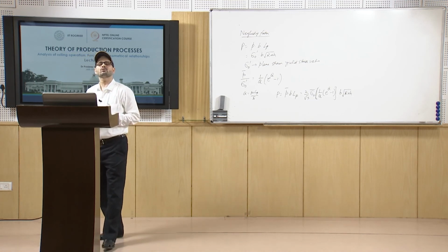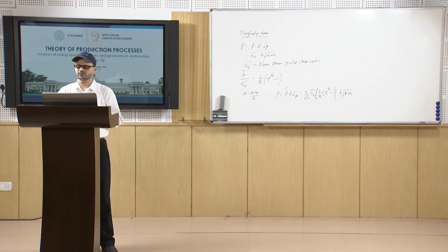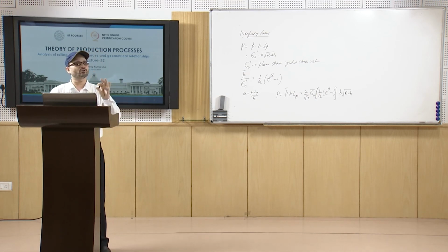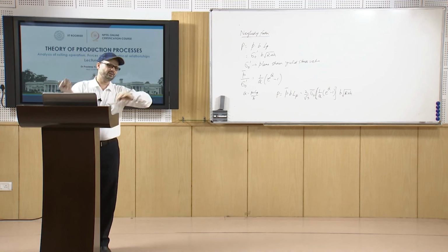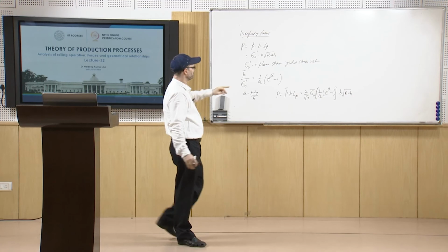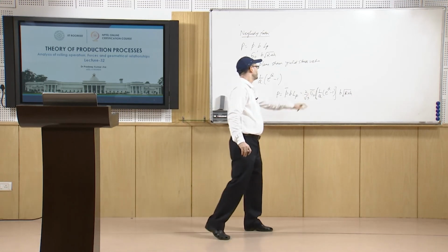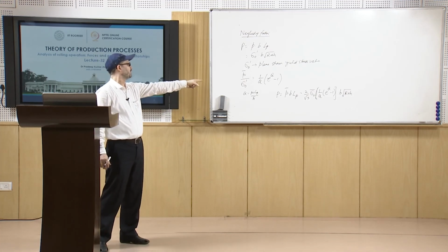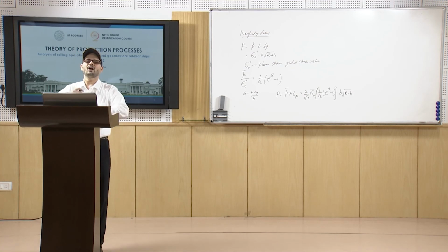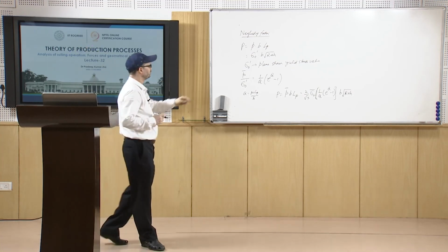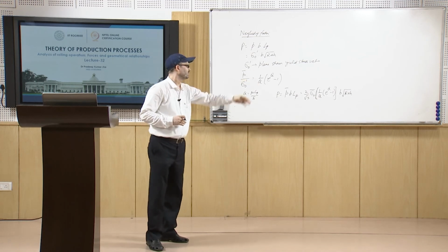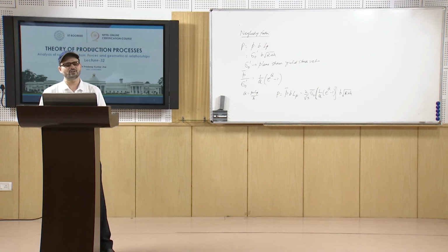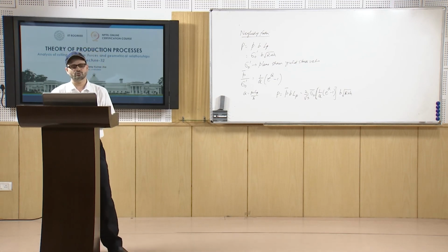In this case, this 2 by root 3 factor is coming because rolling is in the plane strain situation, and the flow stress should be the flow stress in plane strain. That is why, if we recall our previous findings, we get this expression. Once we know this sigma naught bar, which is the average stress value, then finally you can find this rolling load. So, this is how the value of the rolling load can be found out.